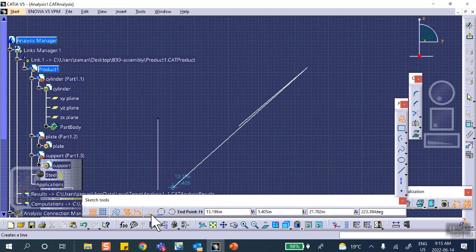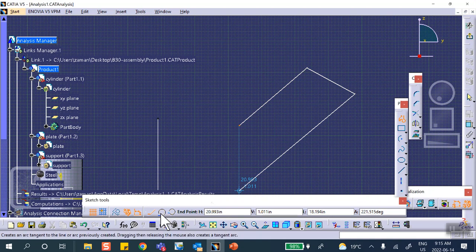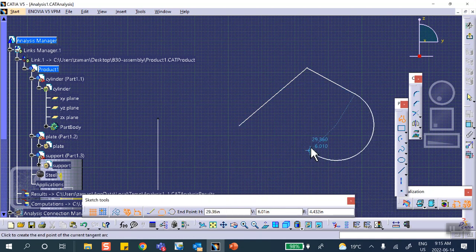If you click on this guy, which is already selected by default, it turns into a line. If you want to turn it into a circle, do what I just told you, or select one of these guys. For example, this, you see that? A circle with a line. I didn't drag it. Those two icons do the job. Line to line, line to a circle with a tangency, and line to a circle with no tangency.